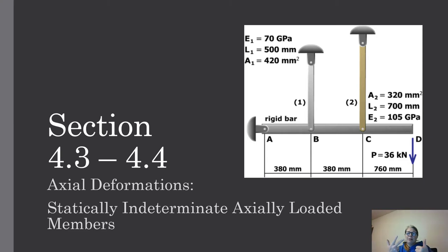I have an x component, AX, but there's no forces in the x direction. So the x equation is not helpful. So I have three, AY, BY, and CY. So I can sum forces in the y direction, okay? That leaves me two more unknowns. I can sum the moments about a point. I could sum them about A or B or C, but I'm still going to have those two unknowns. So I'm indeterminate. Okay, I'm indeterminate to 1 degree.